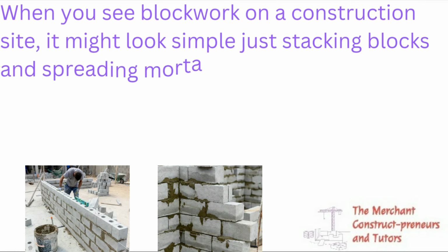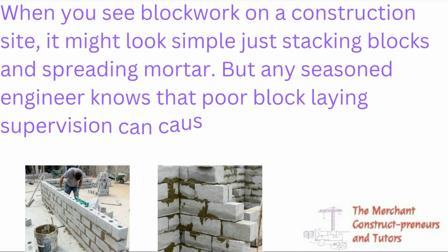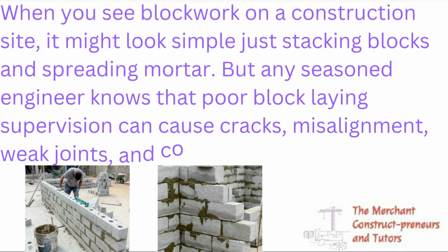So we'll be looking at just a quick description of what we are going to be looking at. When you see a block wall on a construction site, it might look too simple, just stacking blocks and spreading mortar. But any seasoned engineer knows that poor block laying supervision can cause cracks, misalignment, weak joints, and costly rework. So this is just a summary of it. From the images, you can see in the first image well aligned blocks with plumb and everything being checked, while in the second image you see the misalignment, and even the joints are not properly taken care of. They're just left like that.